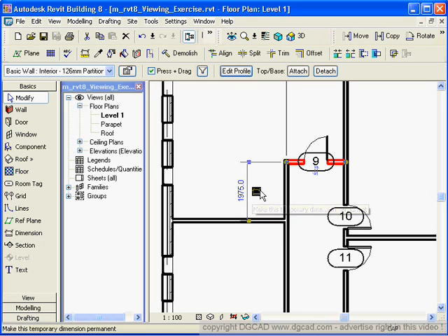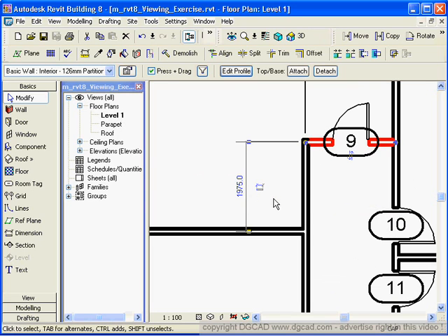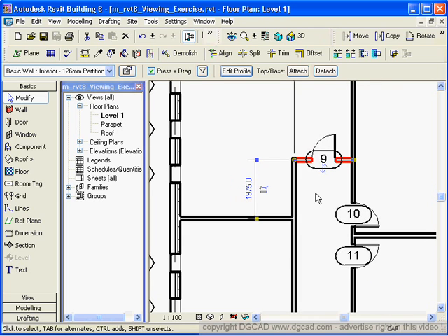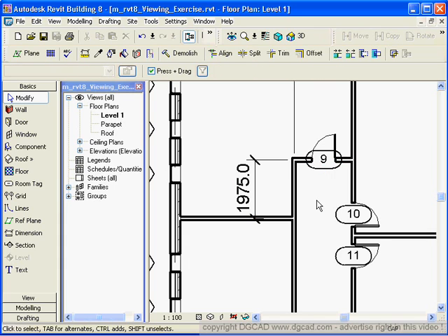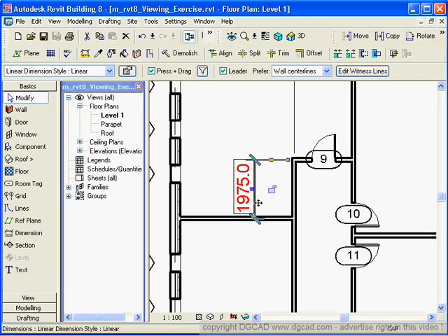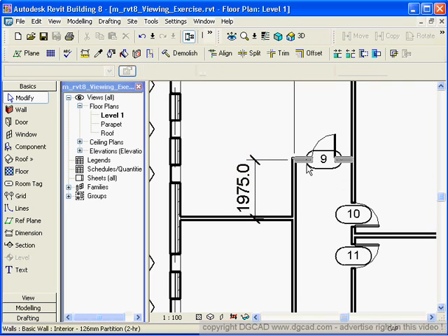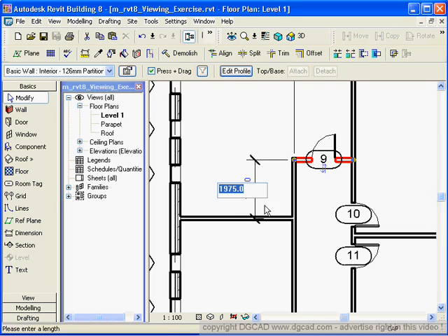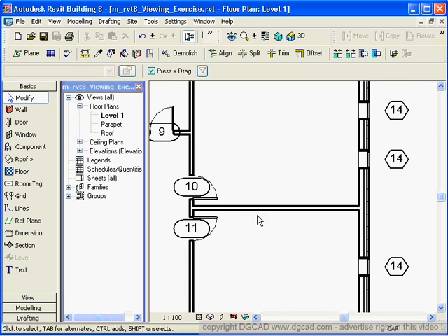If you click on an object, it also shows you this little icon here, which means make it a permanent dimension, which means if I click on something and I hit this, it actually makes that a dimension, and then I click out once and it's done. Now I can go in here and I can change this number. Okay. Now I can't change it right now because the wall isn't selected. First you select the wall, then you click the number, then you make your change, and it'll move. Okay.